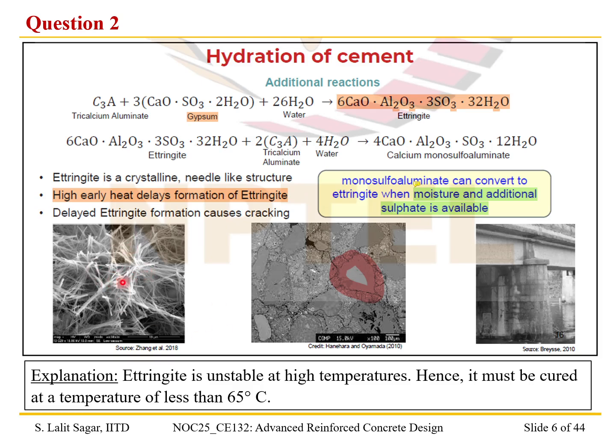So as we already discussed earlier, this is a microscopic image of the ettringite. So ettringite, with its crystalline needle-like structure, has a high volume, and because of the expansion of the volume due to the DEF, there can be cracking within concrete. And as we know, cracking leads to porosity within concrete and other durability issues. So moving on, we can move on to the next question.